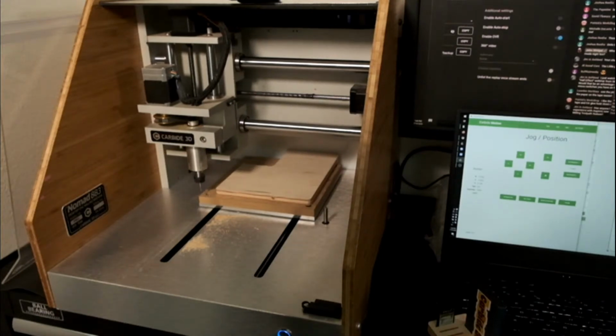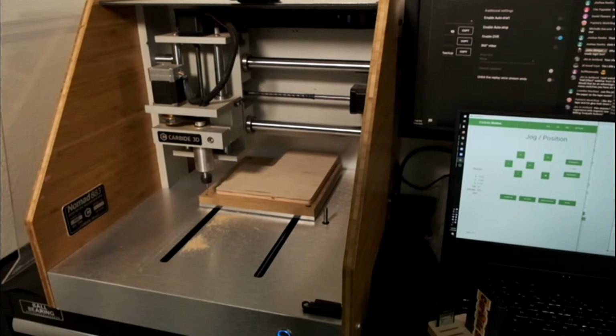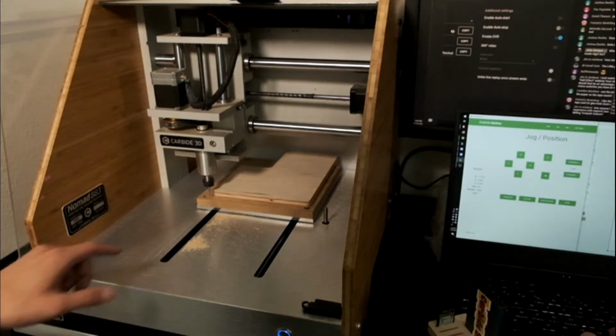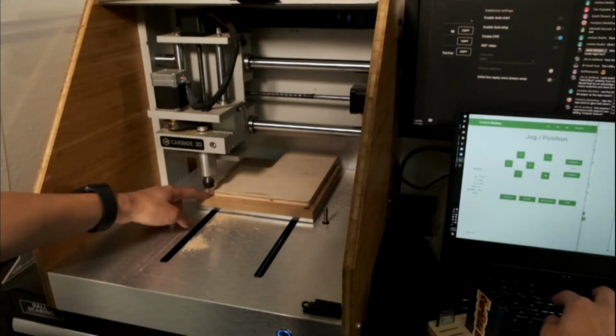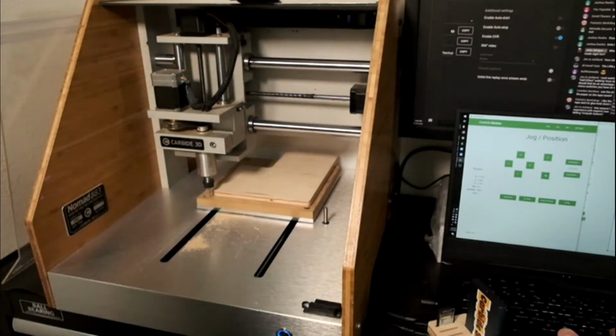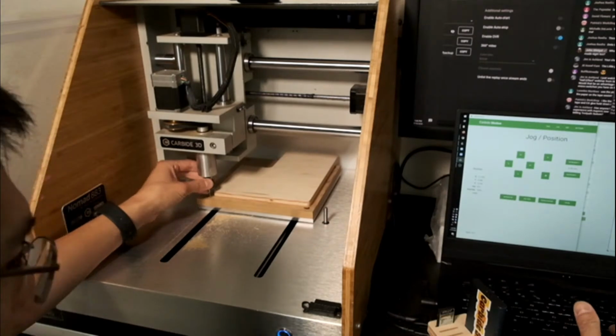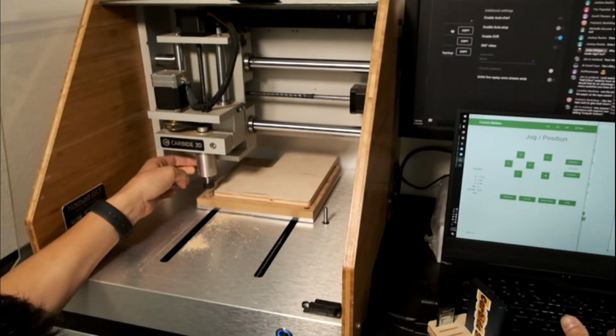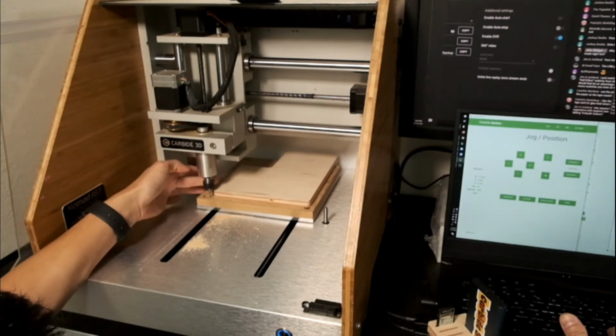And I'm going to find my Z first. So switch to 2 for 1/4 millimeter increments. I'm really just eyeballing this. I need to get it within 0.008 inches of the bottom, because most double-sided tape is about double the thickness of a sheet of paper.